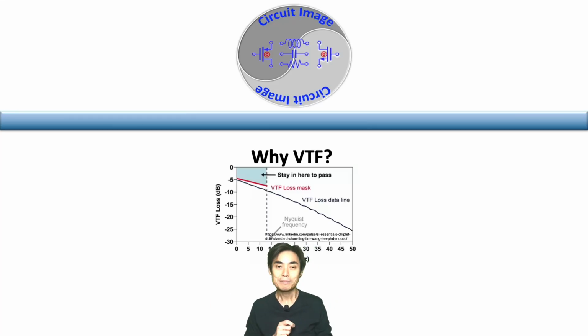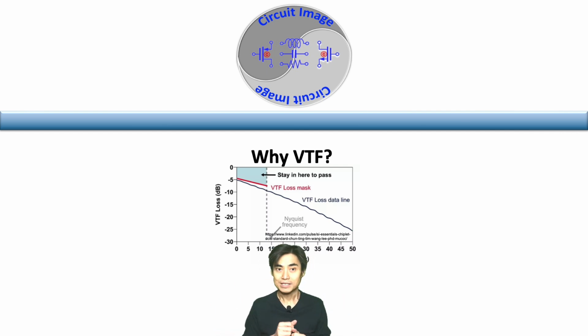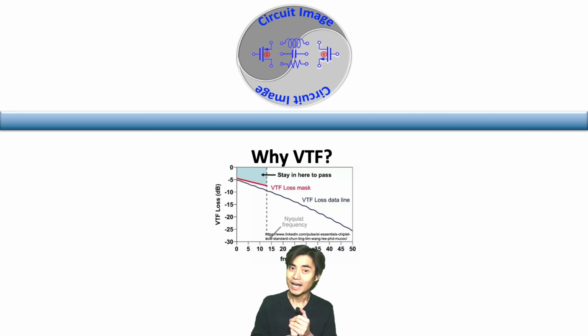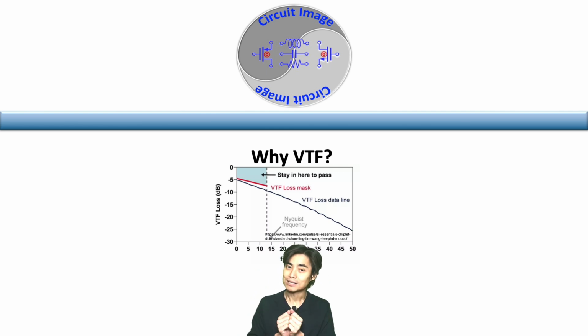Traditional signal integrity (SI) metrics such as S-parameters and time domain reflectometry (TDR) have been fundamental in analyzing interconnect loss, impedance, and reflections. However, they do not fully capture the unique behaviors of die-to-die systems in UCIe-based designs. Due to short interconnect length and complex loading effects, conventional methods fail to translate directly into multi-domain signal quality metrics, making it difficult to ensure reliable signal reception at high speed.